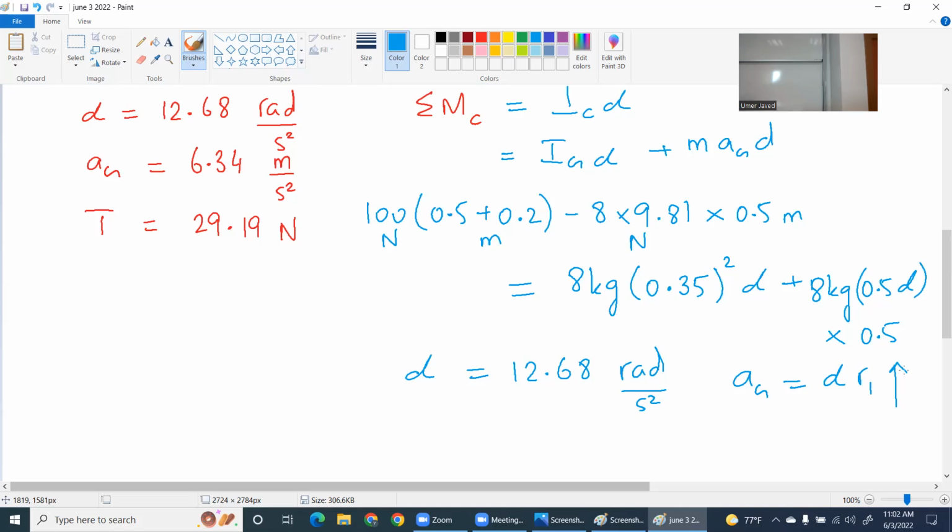So remember, in an exam setting, 80% of the problem that happens is that students are doing summation of moments and they just forget the MAG multiplied by D. It's a problem that 90% of students have. Something to think about. If you are doing the summation of moments about the center of mass, life is beautiful. The moment you are doing the summation of moments about another point, this stupid MAG thing pops up because you have to multiply MAG with the D. Very easy to forget.